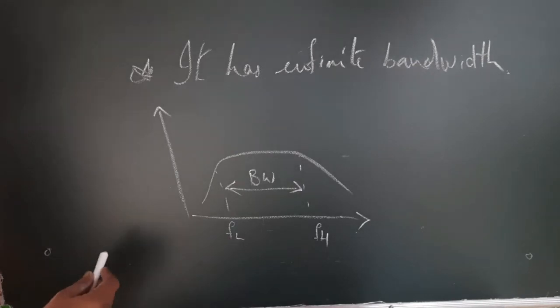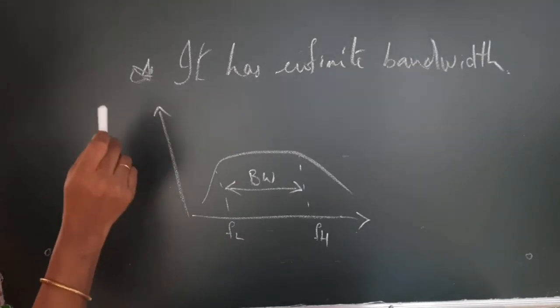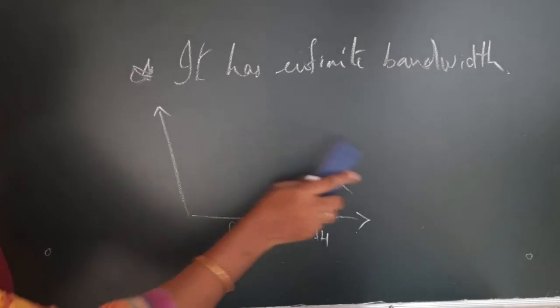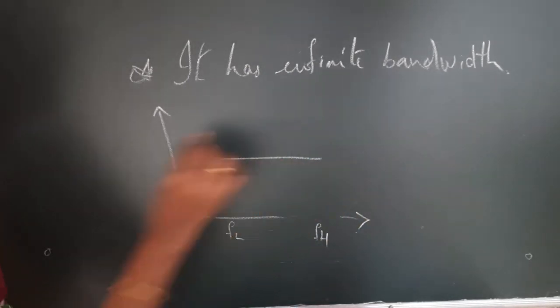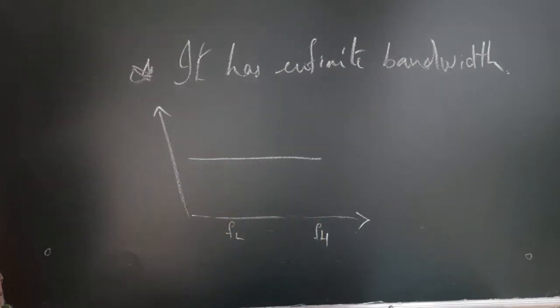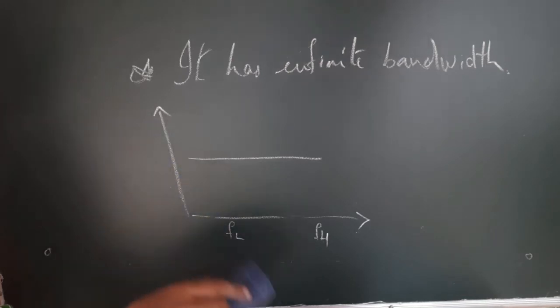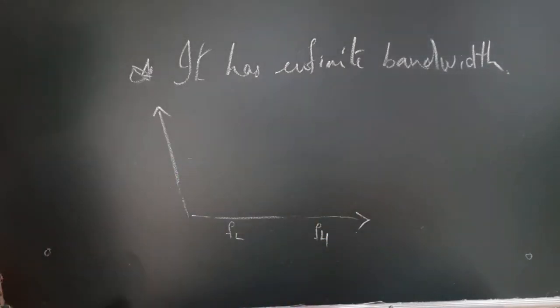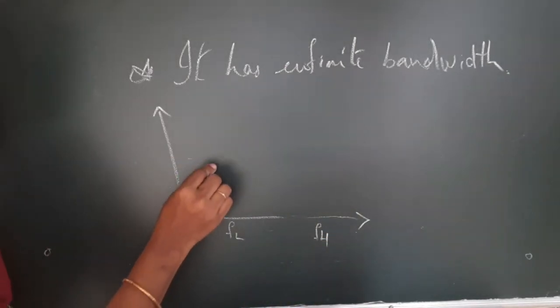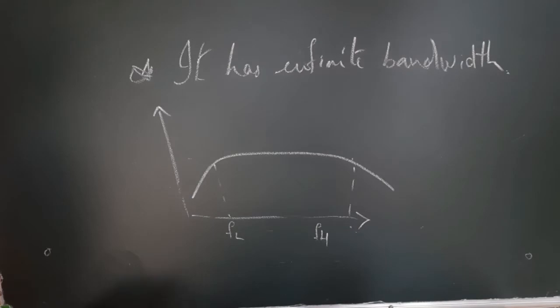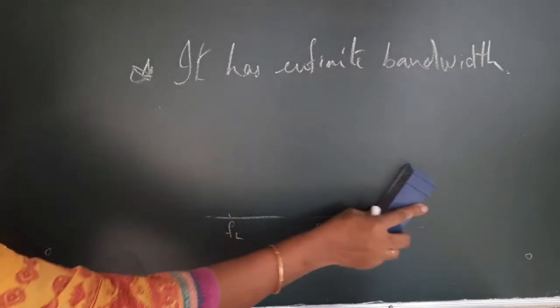When it comes to op-amp, especially ideal op-amp, this bandwidth becomes infinite, or you expect an ideal op-amp to have a frequency response like this, so that its bandwidth is infinite. Now, coming to the practical case, you cannot expect an infinite bandwidth, that is a constant gain throughout the frequency, but you can expect a high bandwidth for a practical case. So, this would be the bandwidth for a practical op-amp, though for ideal op-amp it is said to be infinite.